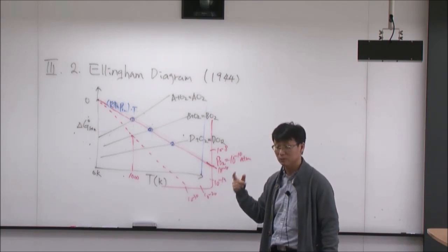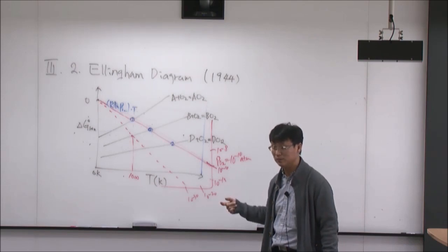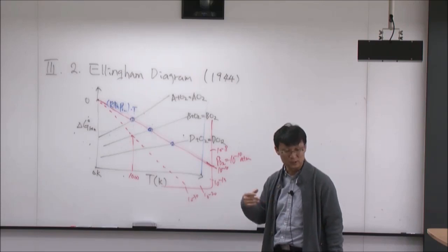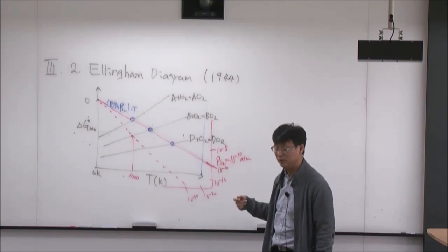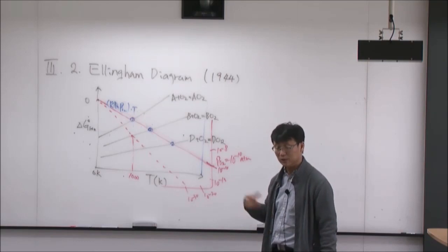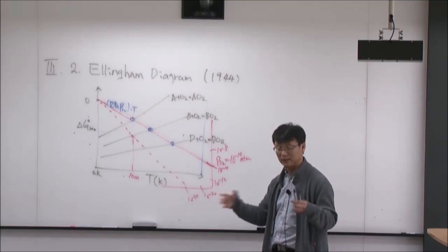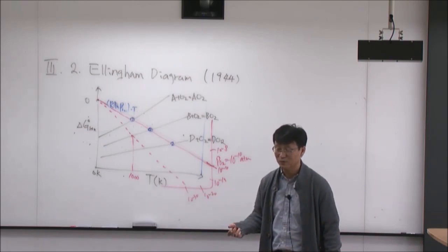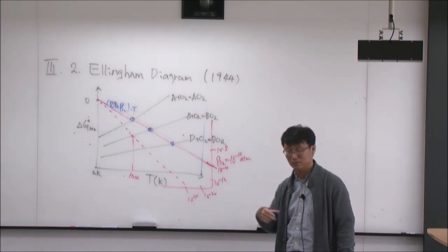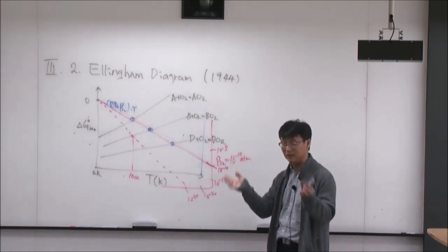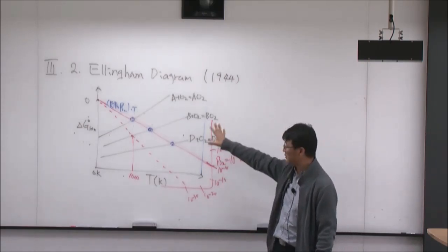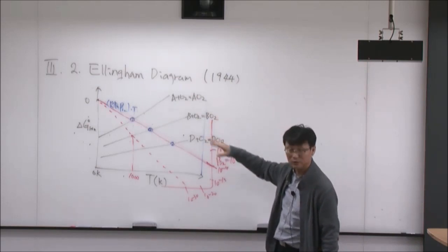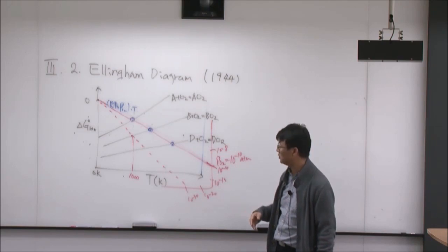There's no solid solution or liquid solution. Everything is pure solid or pure liquid. The only thing that changes is the partial pressure of oxygen. That's one of the weaknesses, because when you go to the real plant, the industrial scale, most of the matter is not pure anymore. So we have to consider the interaction between one element and another inside of a solution. But nevertheless, if you consider this almost pure material, you can still use this to judge what the partial pressure of oxygen is.